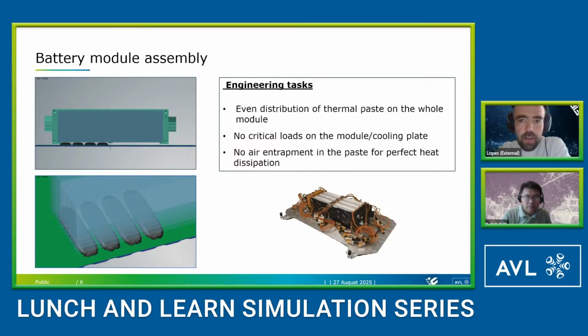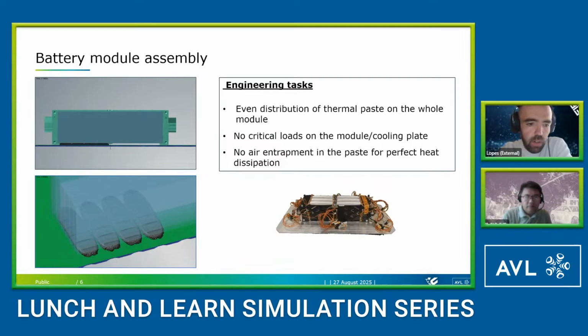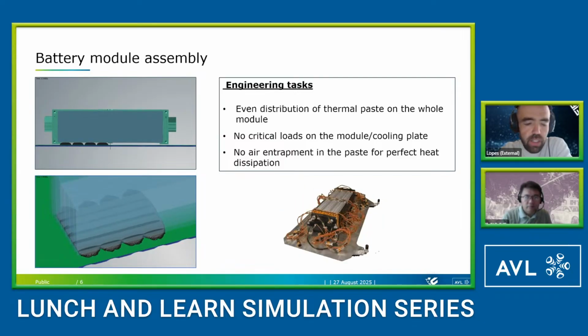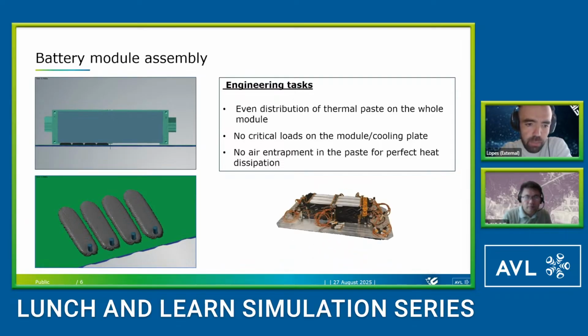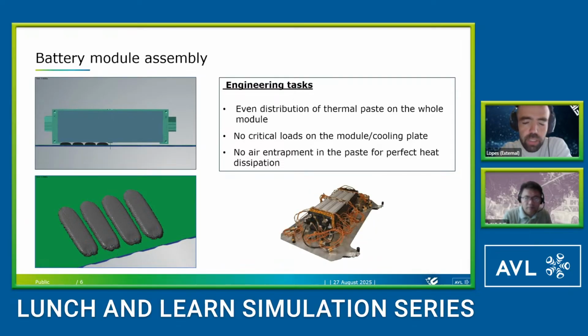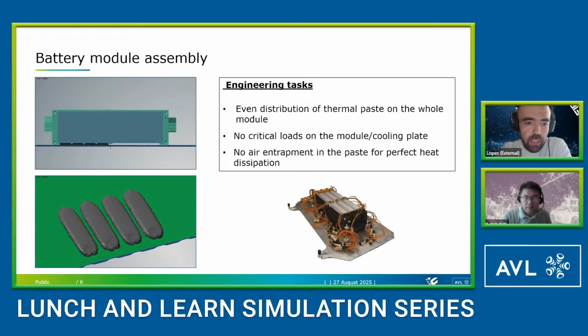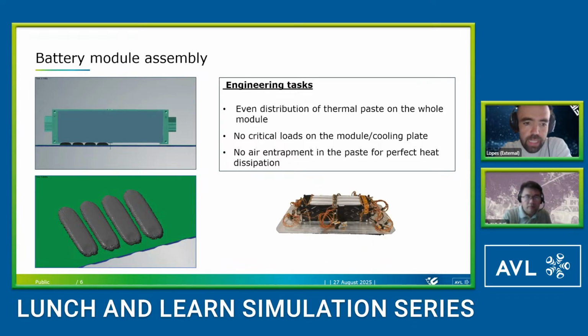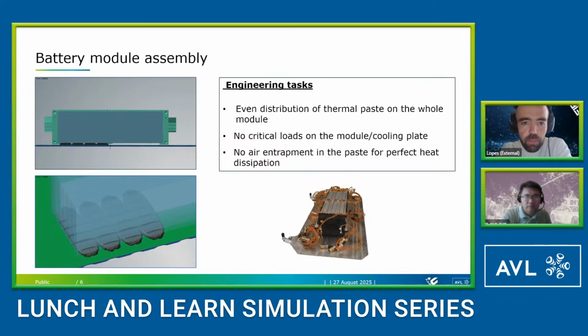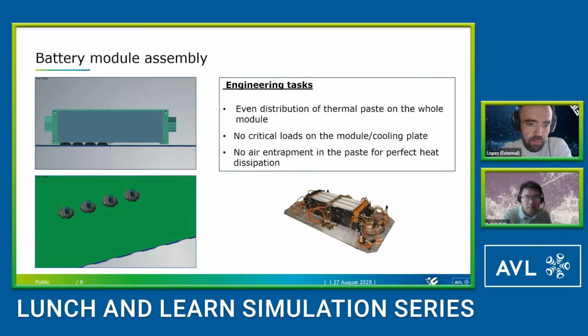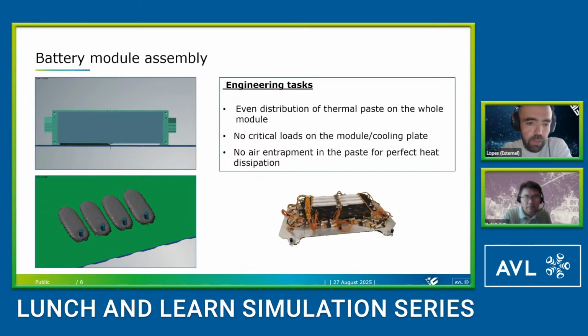And we use a gap filler, or a thermal paste as we call it here, to help improve the heat conduction between the battery and the cooling plate, which is in green at the bottom. And in the case of this simulation, we used a Carreau-Yasuda model to model the viscosity of the fluid.